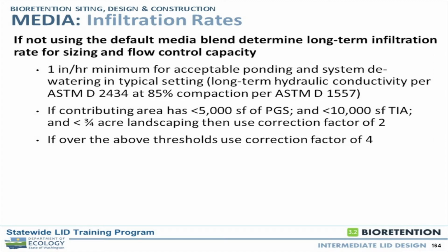Now you're designing. You've built your media and you're going to design your bioretention. And now there are actually correction factors for the media. So I want to be real clear here. We talked about correction factors for the subgrade, right? What were some of the guidelines? Site variability, the test you use, right? Correct, and there are correction factors that go with that for the subgrade. Now we're talking about different correction factors. We're talking about correction factors for the media.